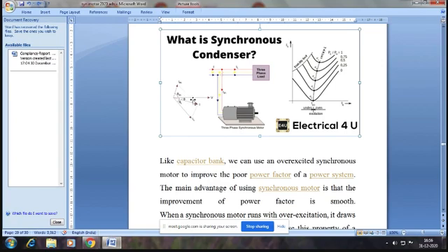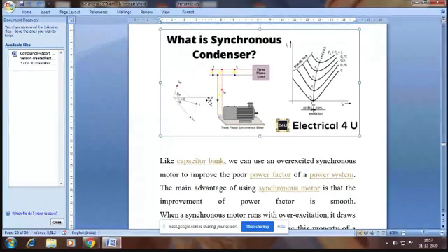That's also shown here. Therefore, the effective or resultant current is I, that will lag V by a smaller angle. Look, here it is clear, isn't it? Yes, sir. Which means the power factor has decreased or increased? Lagging loads. Okay, has the power factor increased or decreased? Increased, sir. The lower the angle between voltage and current, the higher the power factor. Correct? Yes, sir. This is what effectively the synchronous motor does in a network.